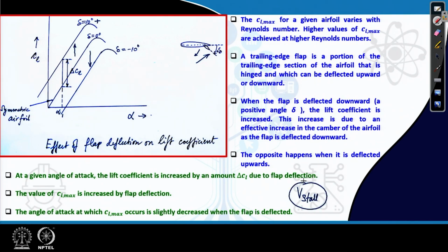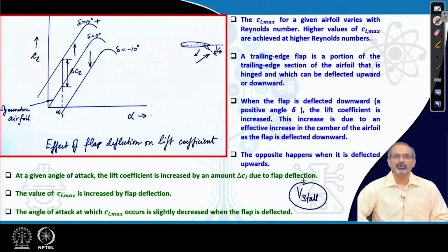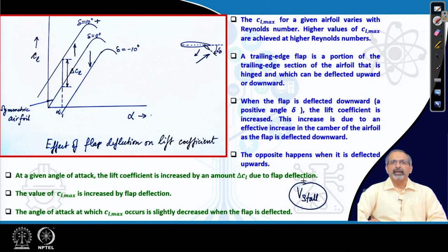Of course, remember that when the airfoil section is applied on an aircraft, it is applied on a finite wing. It is not on an infinite section, and therefore, the end effects of such a finite wing would influence the aerodynamics, which we will see in later lectures, but for now we are concentrating more on the sectional behavior of such a wing. Thereby, we are looking at the airfoil characteristics.